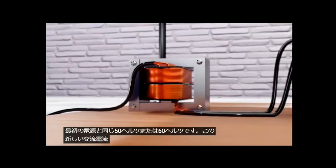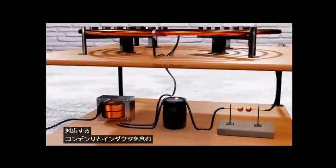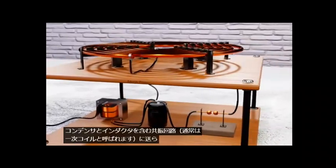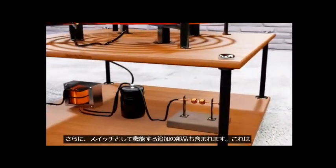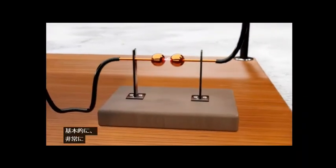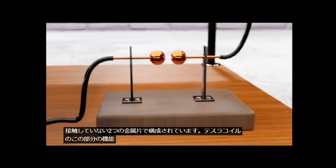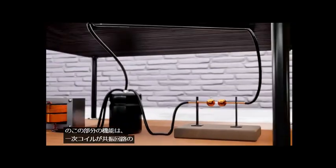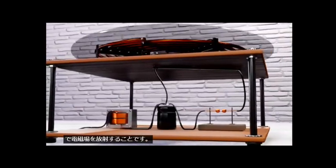This new alternating current is brought to a resonance circuit with its corresponding capacitor and inductor, which is usually called the primary coil, also including an extra component which serves as a switch, which basically consists of two pieces of metal that are extremely close, but not touching. The function of this section of the Tesla coil is that the primary coil emits an electromagnetic field with the frequency of the resonance circuit.